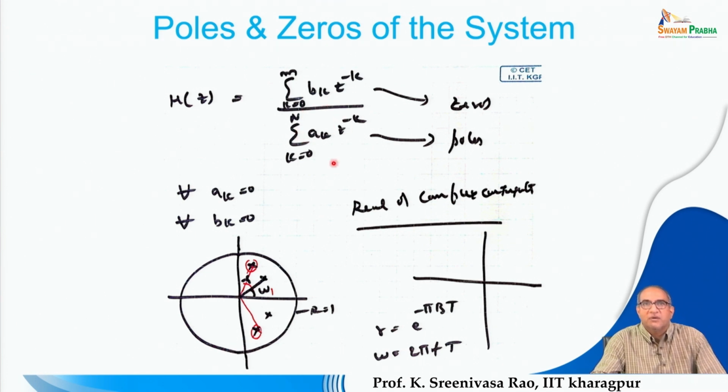If you solve this all-pole system, because the coefficients are real, the roots will be either real roots or complex conjugates. We get real roots from the linear factors, and complex conjugate roots from the quadratic polynomial. That means by solving a quadratic polynomial, sometimes you may get real roots and sometimes complex conjugates, depending upon the discriminant value. Therefore, here we will try to analyze the poles of the system transfer function, right.